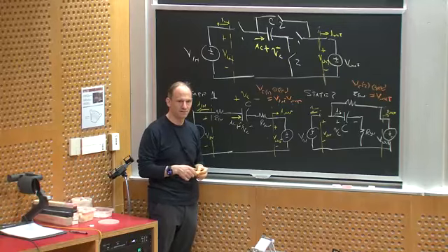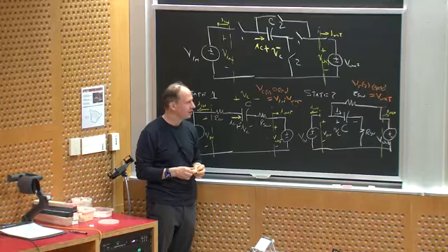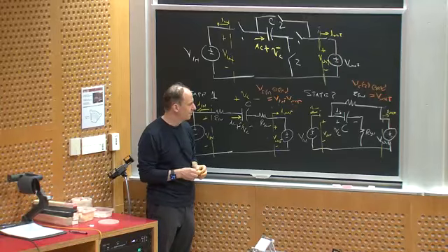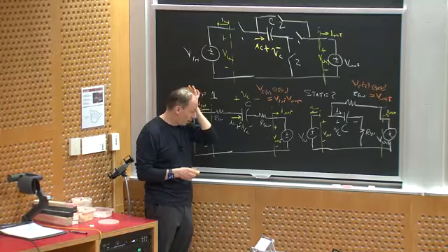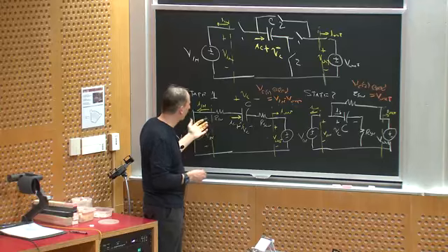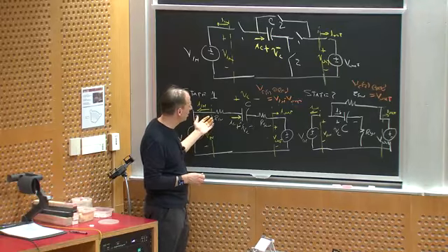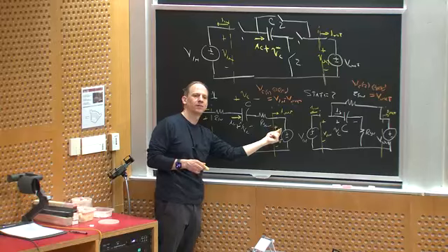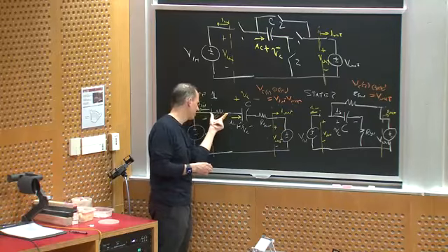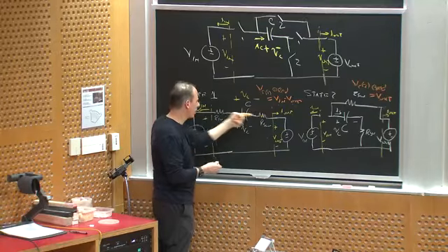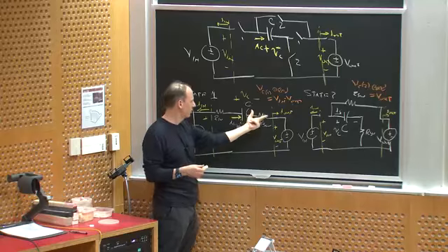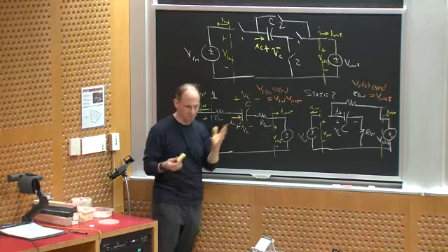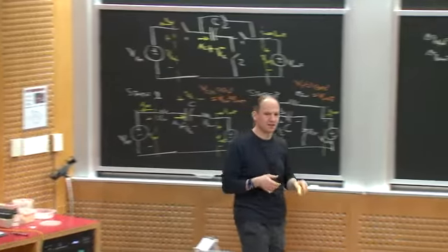But wouldn't the on-state and off-state voltages change? Like wouldn't there be potential differences across the resistors? Well, if I've assumed that the capacitor is fully charged, the voltage across this resistor went to 0 by the end, right? The only assumption I've made is that this capacitor charges. Once the capacitor current goes to 0, these voltage drops go to 0. We'll relax that assumption shortly.